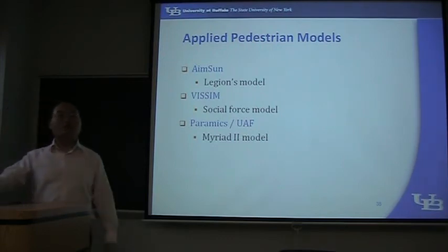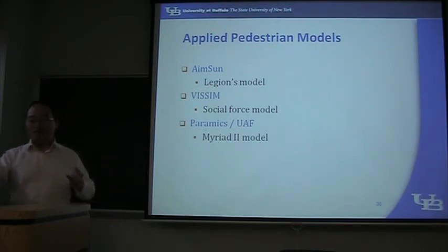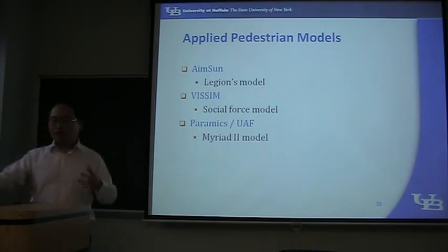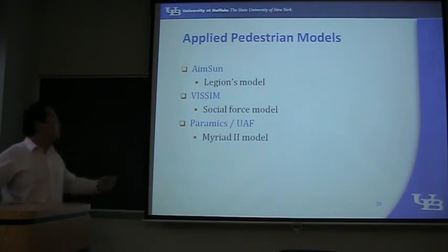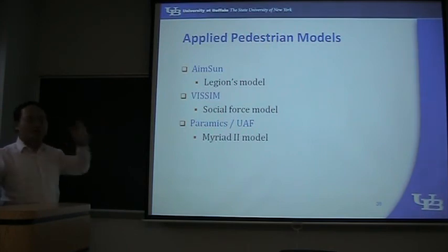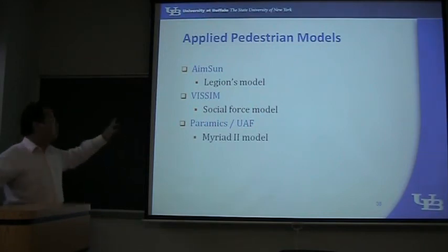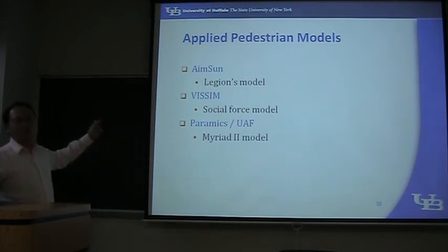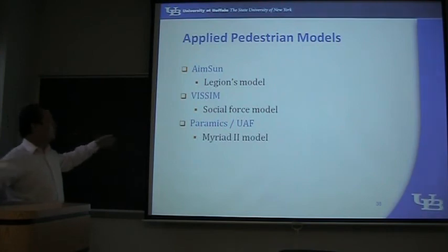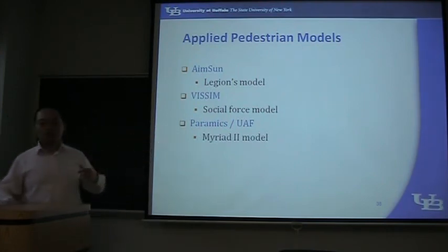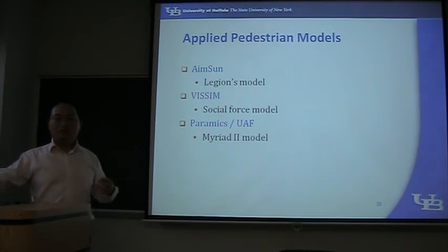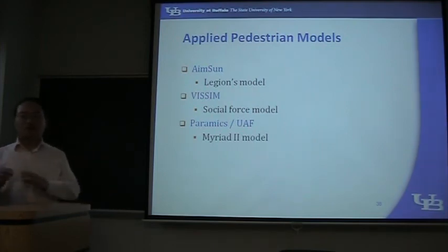Among the simulation tools we introduced, there are 3 that have pedestrian models. The first one is MSOM. MSOM has a model which is developed by another company called Legion. So if you want to do some research about MSOM's model, just search Legion's model. For Vissim, it has another well-known model called the social force model. So the interactions are modeled by the force between individual pedestrians.